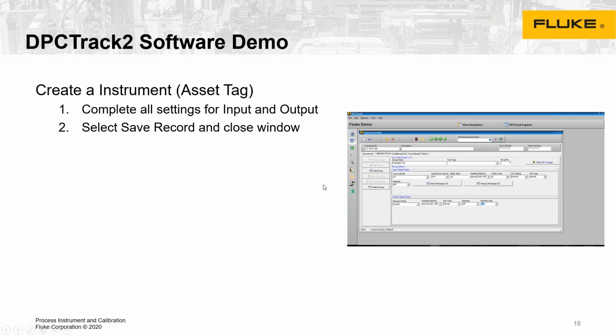So in the same capacity, we would want to set the source to thermocouple, turn on loop power, set a delay, type K thermocouple using the internal CJC setting and a normal unit type. We would also want to put the measurement setting in current with all other settings being normal. There are availability to have min max settings, user entered variables.